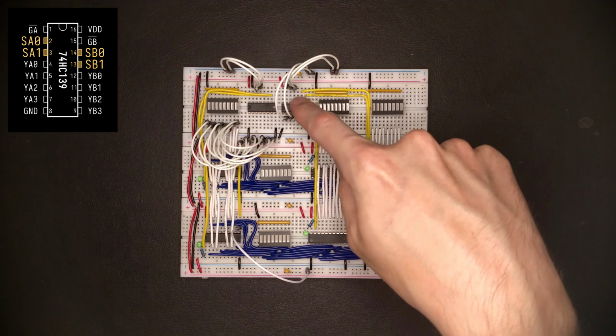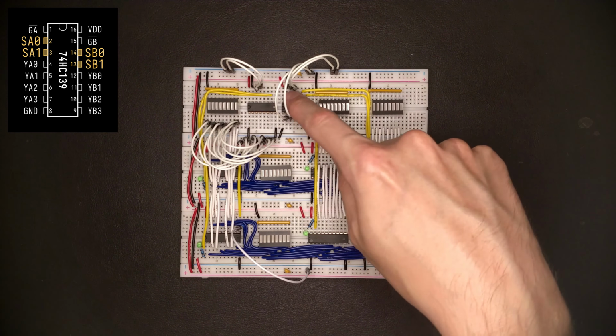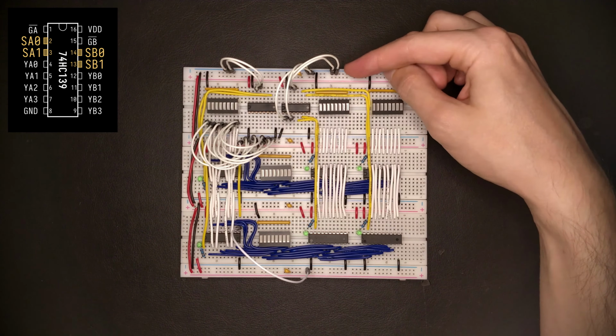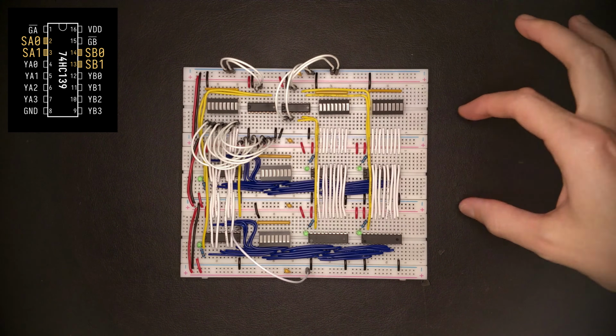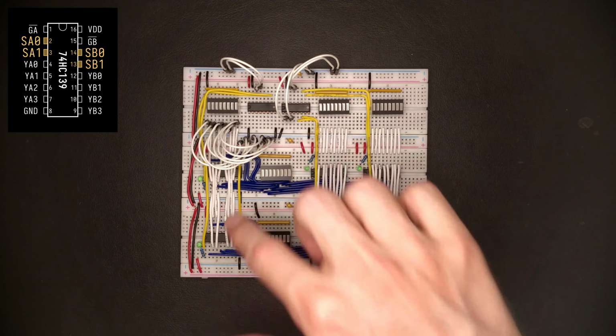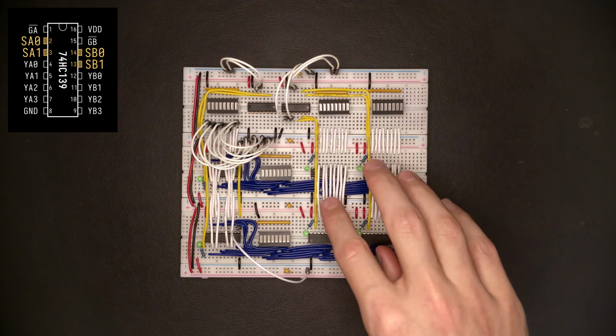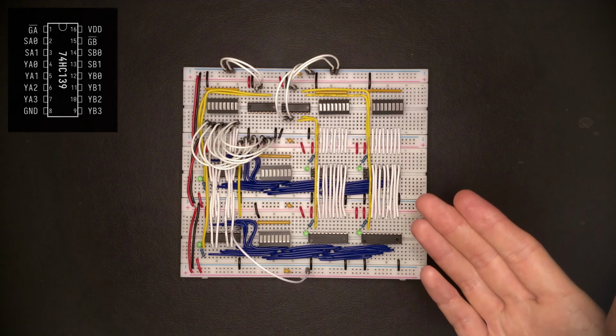So I've connected the 3 register address inputs here to all zeros. So these should select register 0, which doesn't exist, for reading and for writing. And so in essence, none of the registers should actually be selected to do something. Let's give this a try.